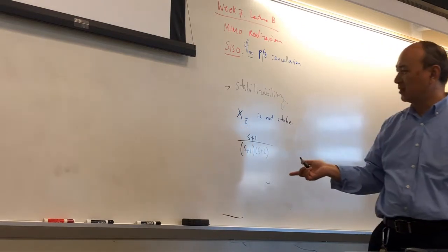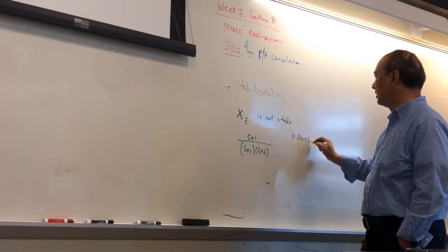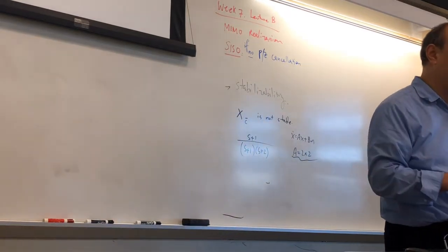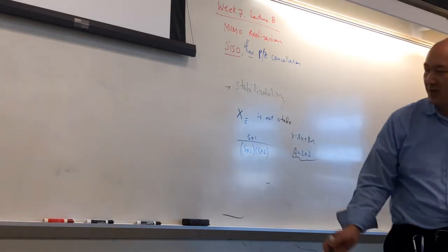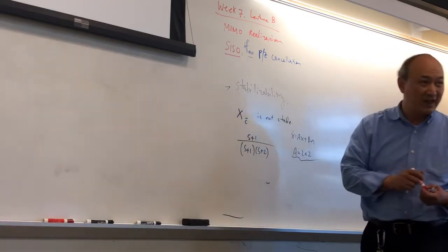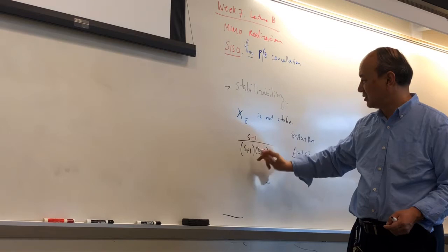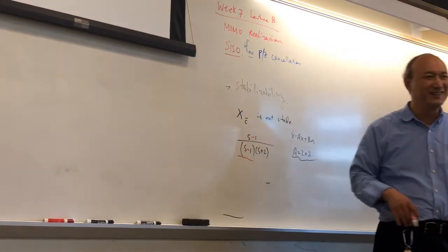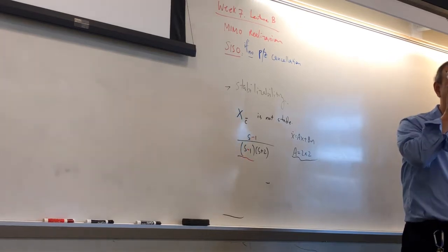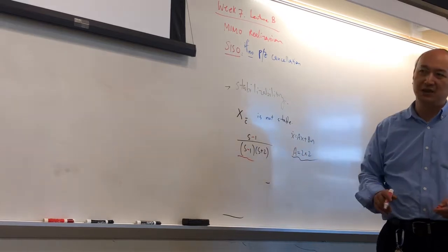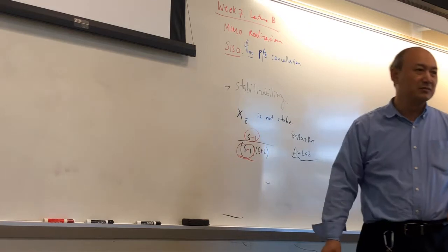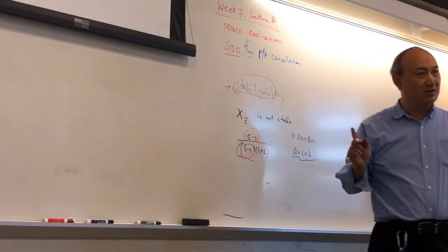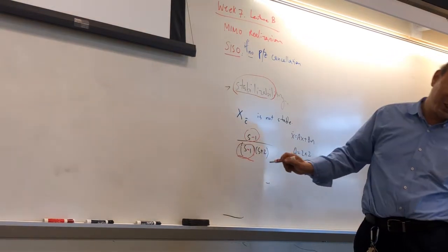So when you do this, if you do a second order realization, x dot is Ax plus Bu, where A is 2 by 2, then this realization will be controllable, could be unobservable, okay? Could be, so we have seen this example. But did you ask yourself, what if you have something here? You have an unstable pole cancellation, okay? So although you still can talk about realizability or controllability, because you canceled out something unstable, although you can cancel it, this system is already not stabilizable. Okay, it's not stabilizable because there's something beyond your control, which is unstable, by the way.